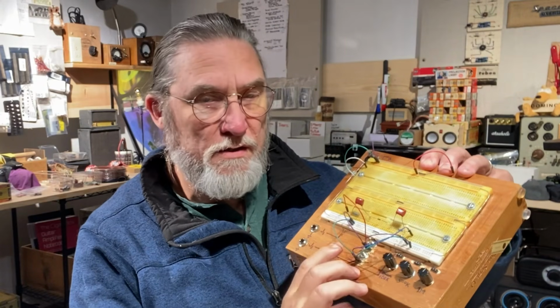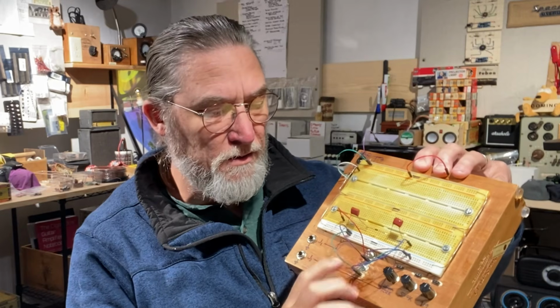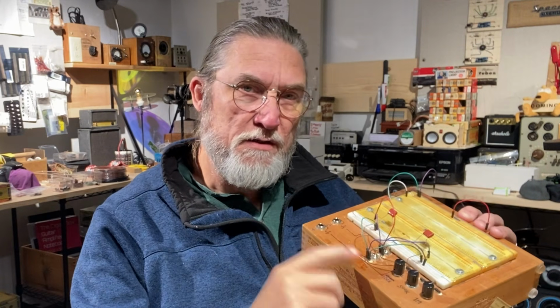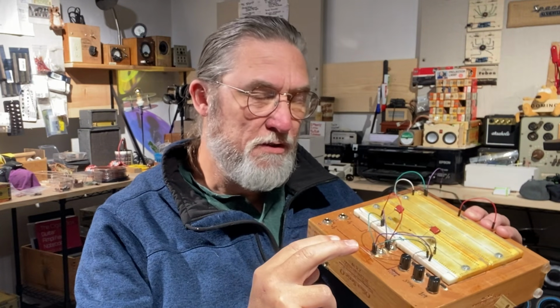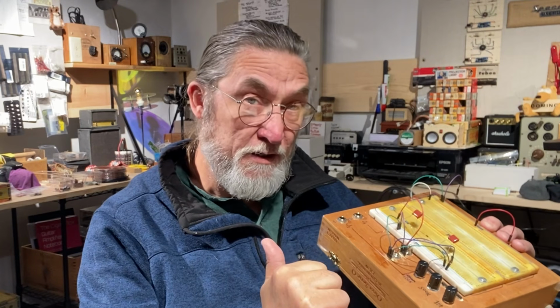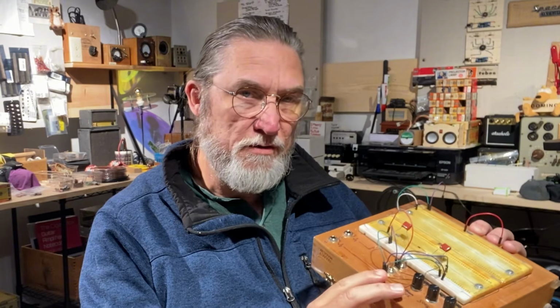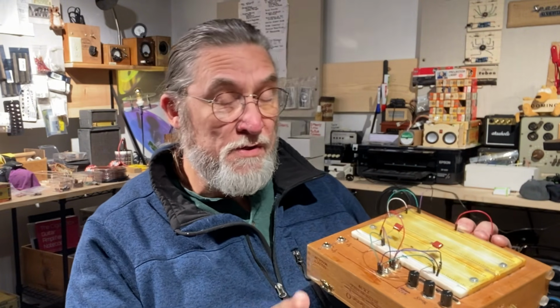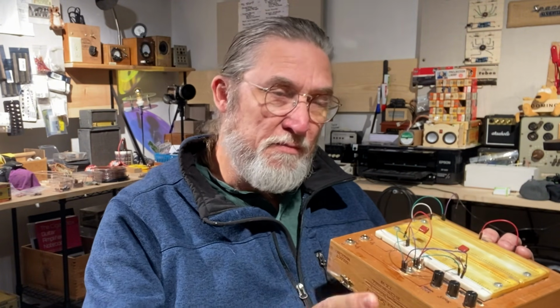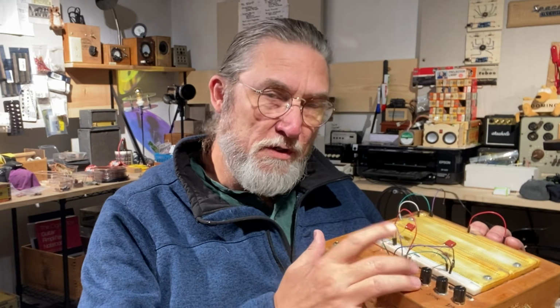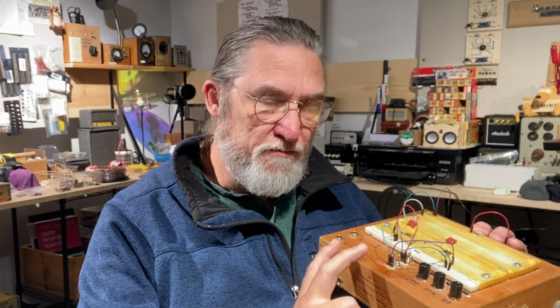In my previous video, I demonstrated how I could use a simple switching diode to act as an audio switch. If I forward biased the diode, I could allow an audio signal to come through, and if I reverse biased the diode, it would block or prevent the audio signal from coming through. Now, there were some problems with this, and somebody made the comment that you will get some clicking and some popping when you're switching the voltages back and forth.